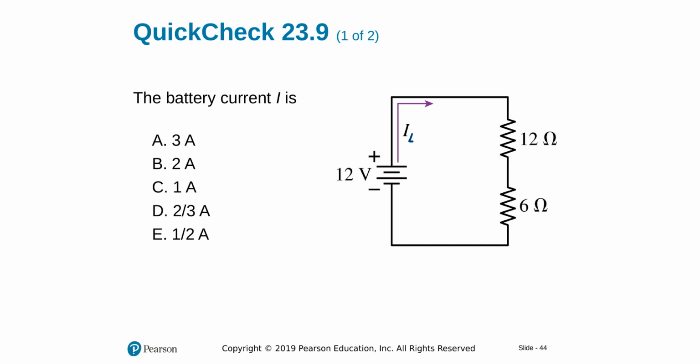What is the total current drawn from the power source? That's the question here. I'll call it I total, and that's always equal to delta V total divided by R equivalent, and this would be my delta V total here, 12 volt. I already know delta V total. I'm going to find R equivalent, insert it in, and find I total. What is R equivalent?